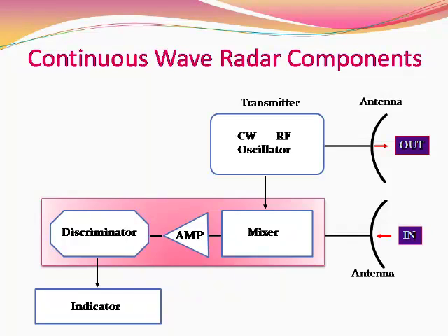We shall see the block diagram of a CW radar system. So from our knowledge so far, we are to send a continuous signal from a transmitting antenna. So the transmitting antenna is connected with a high frequency oscillator which generates this continuous wave signals. The transmitted signal will be towards the target. The target is going to reflect them. Then the received signal from the target, or what we normally call as echo, is going to be given to the receiver block.